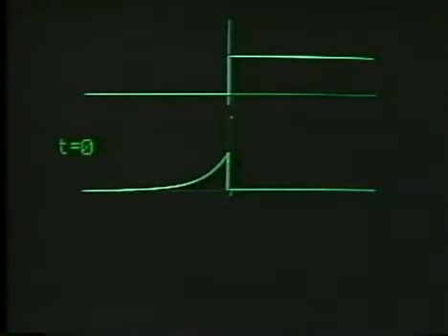Again, the input that we consider is a step input. And again, we use an impulse response, which is a decaying exponential. And to form the convolution, we want the product of x of tau, not with h of tau, but with h of t minus tau. So we want h of t time reversed, and then shifted appropriately depending on the value of t.